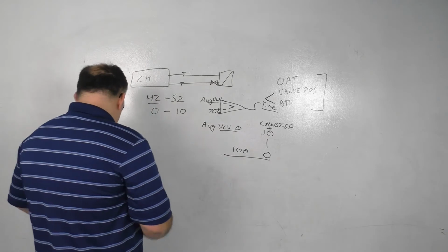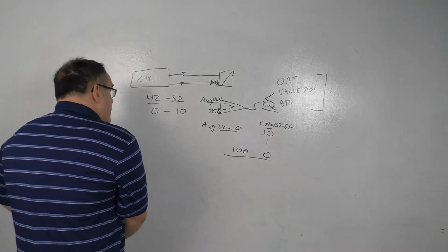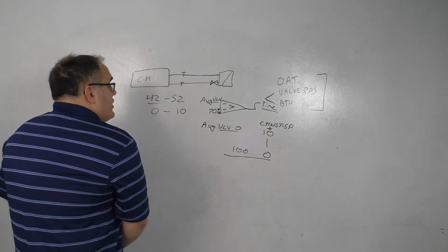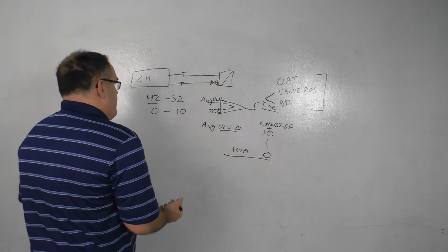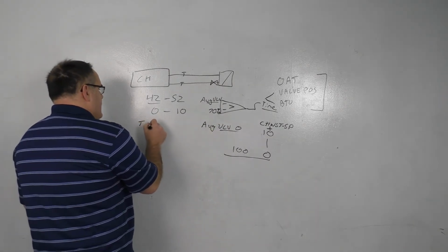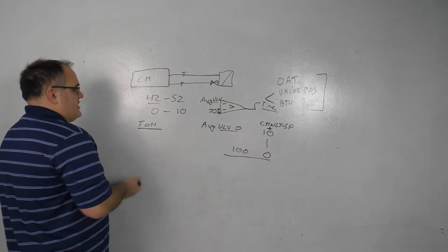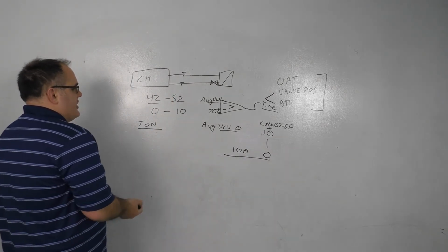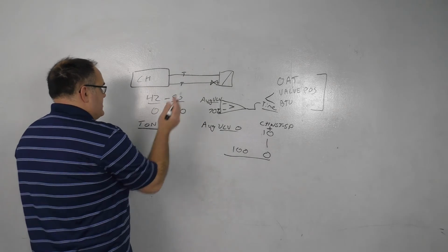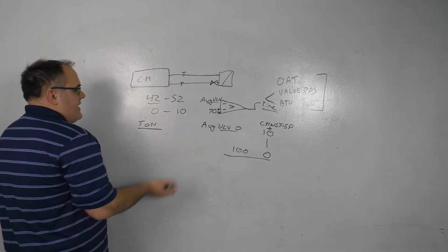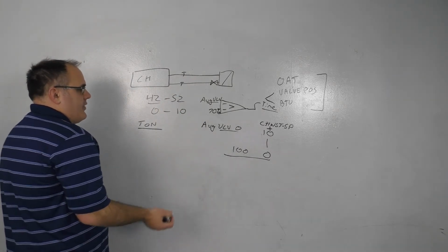So once you've done that, what you're going to do is say, hey, I've got my BTUs. I've converted that to tons of cooling. And then you're going to look at your chiller, and you can actually go and say, hey, this chiller's rated for so many tons. I'm going to increase or decrease the set point.